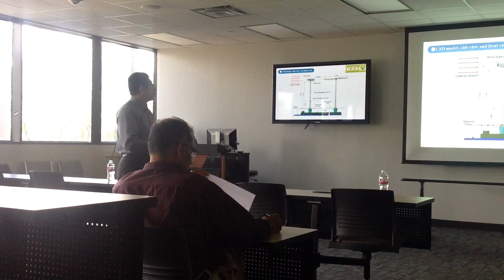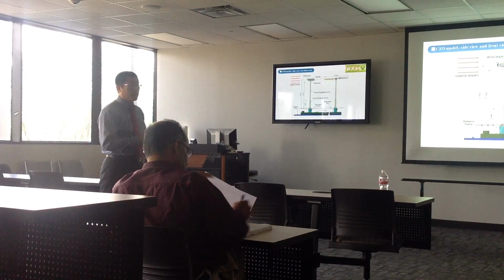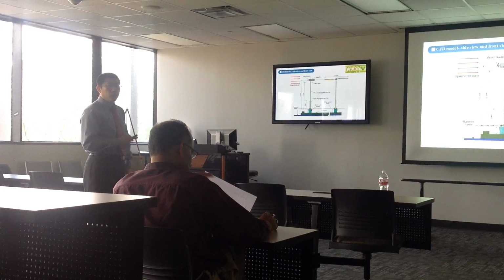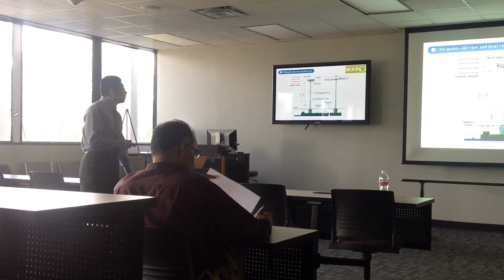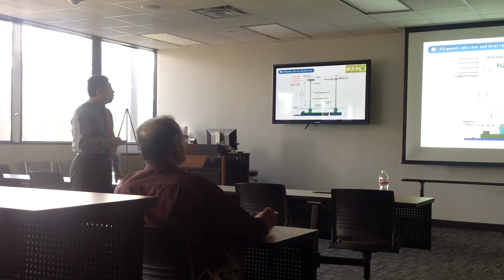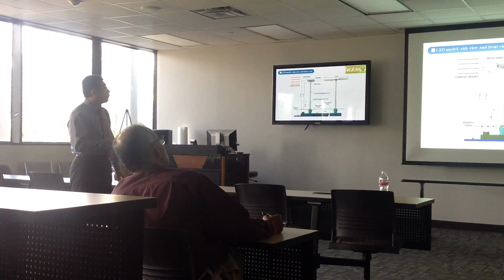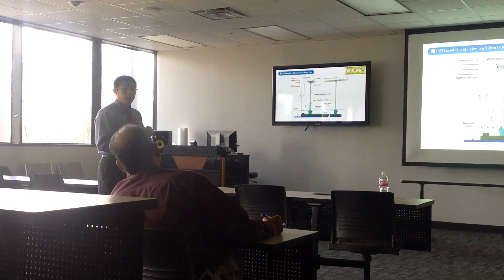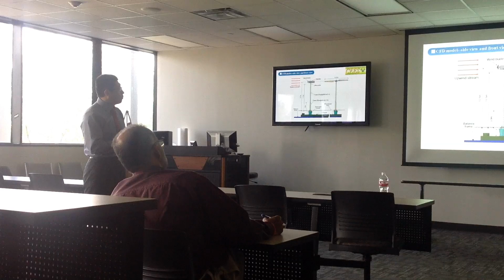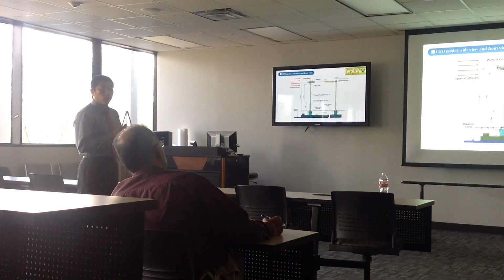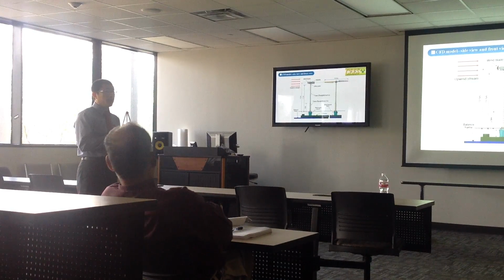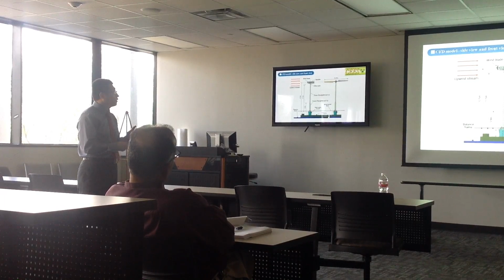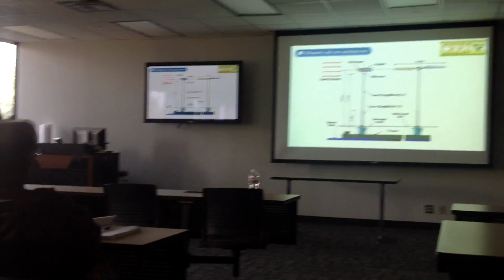This is the wind turbine system model for our simulation. Based on many researchers' work, we found that the tower and also the nozzle have little influence on the simulation result of the wind turbine blade. So in our study case, we only studied the wind blade. By doing this, it can reduce the simulation time. That's the benefit.